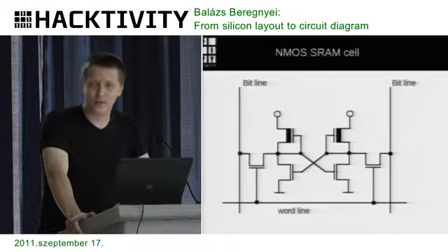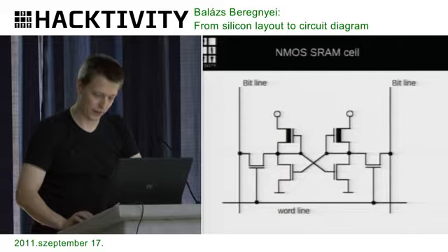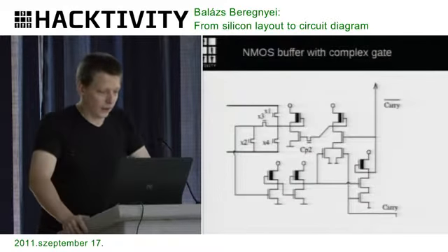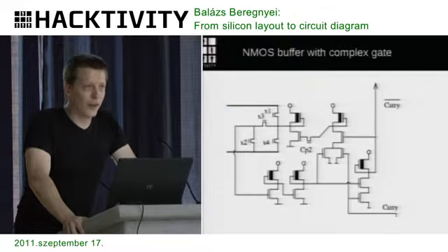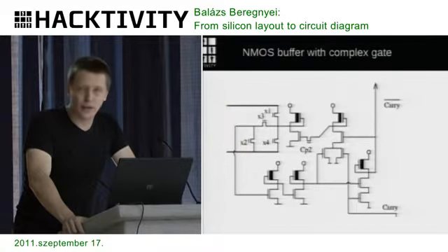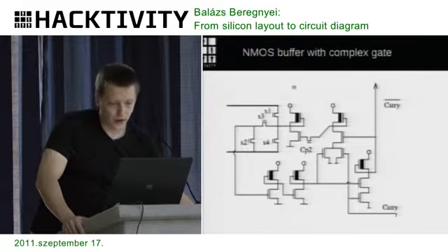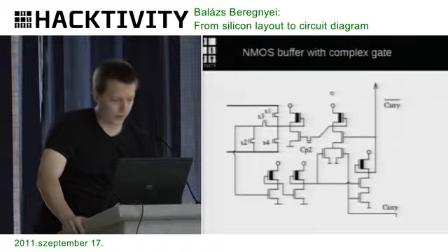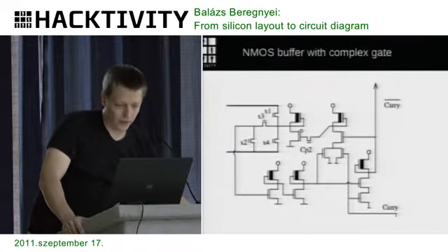Now, of course, we can do that in the Commodore time. This has less than 4,000 transistors, of course, cache not included. This is the most complex gate in this structure. You need to understand that these 2 gates in the middle are also cross-connected, not inverters but gates. So they store 1 bit.